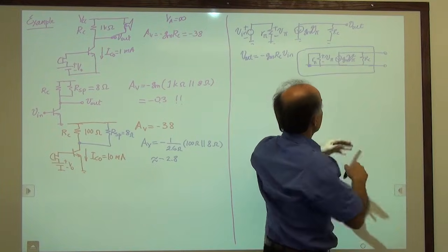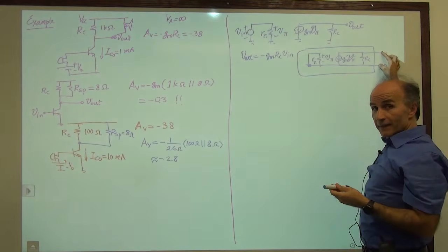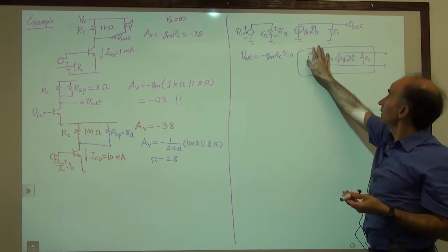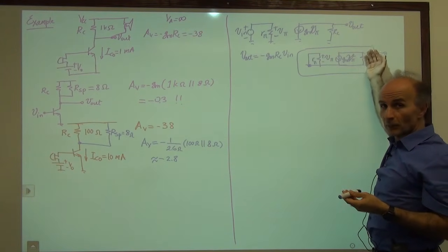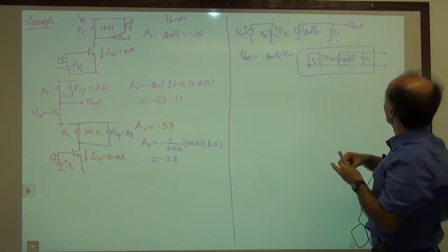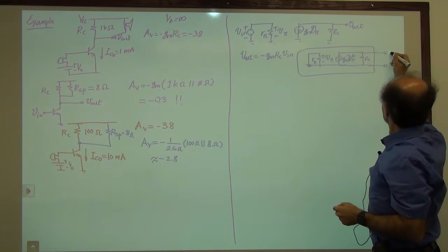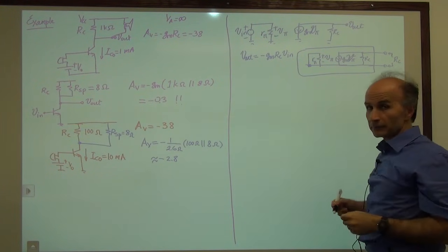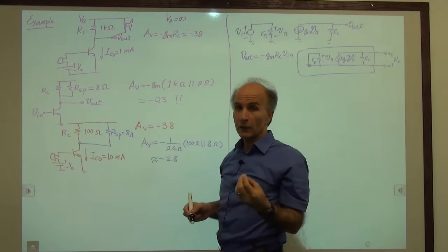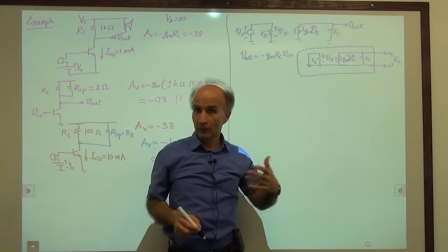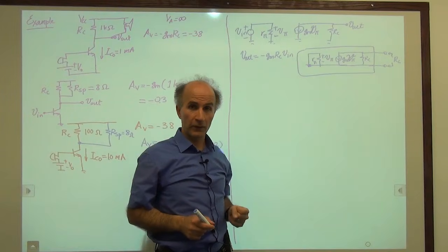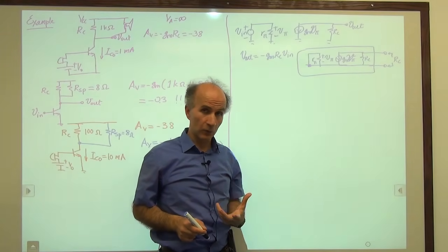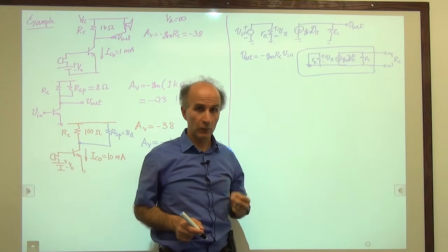So if I sit here and try to measure the resistance, I see Rc. I don't see anything else. This is open. This is gone. This is not connected to this part anyway. So we have only Rc. So the resistance that we see measured between these two terminals is Rc. And this is why it's so important that you be comfortable with Thevenin, Norton equivalents, and all these things from basic circuit theory, because we use them here left and right. They are our analytical tools. So you have to be very proficient with using them.